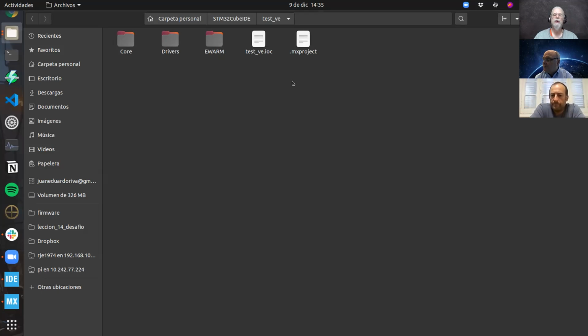But my point is, you don't have to know what the board is. You don't care. You just want to say, here's the process that I'm using. Because when you select a board, it's just taking all the extra stuff that somebody's defined. If you select a discovery board, it says, oh, you got this fancy audio chip on the board, and you've got 4 push buttons on the board, and you've got 6 LEDs, and it's got a bunch of other stuff. You don't have any of that stuff anyway, and you don't care. You just want to say, here's the processor, and you load the code in, and everybody should be happy. You don't have to specify your actual board anywhere, because that just adds extra stuff that you don't want anyway.